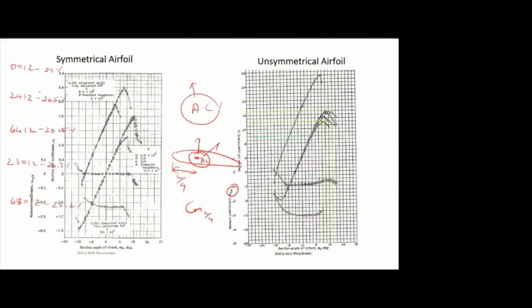Another simplification is, if you want to test 10 models, then for every model individually you have to find the aerodynamic center, and exactly at that point you have to hold it. Instead, they are taking 25% of the chord as the reference point to hold the aerofoil. Initially we started with the center of pressure, then we thought aerodynamic center is better. Finally, they went for 25% of the chord, because even if I give 10 aerofoils, you can simply go for 25% and proceed with the testing.